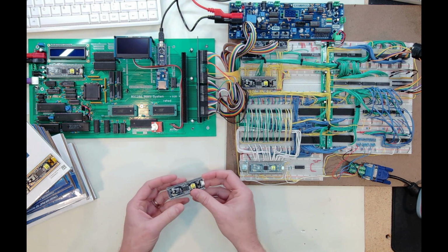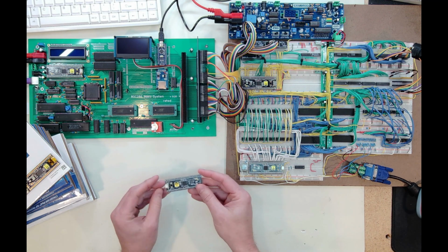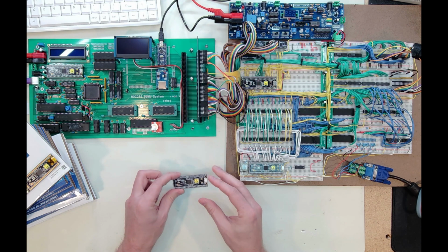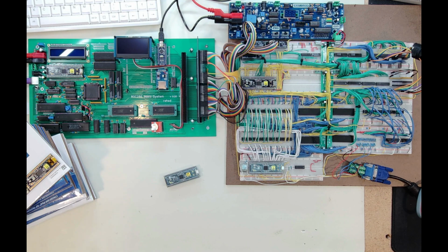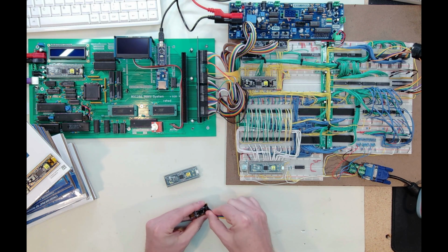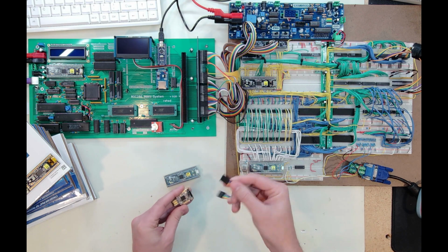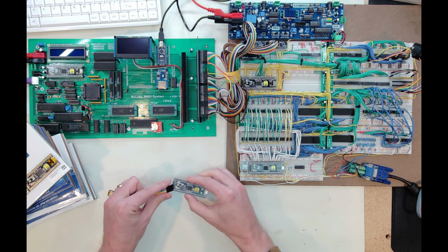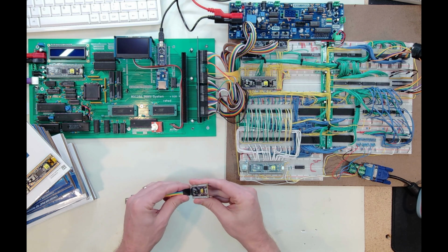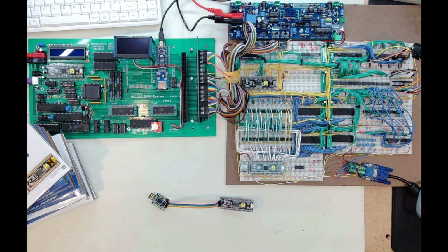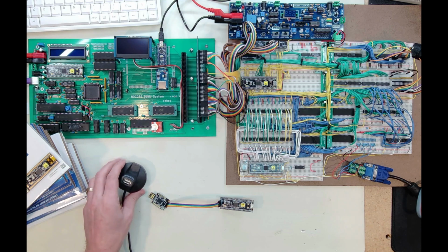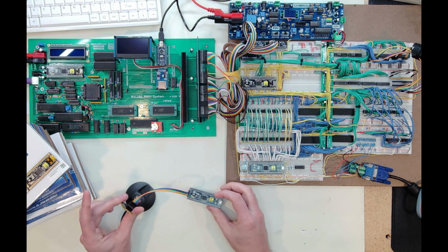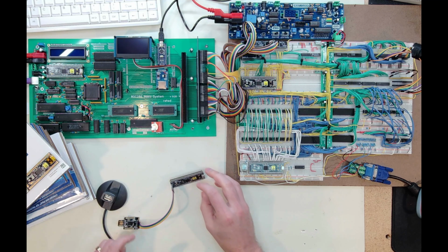So this one, I've done that soldering. I've got all my pin headers put in. I've got this up here so that I can do the programming. And then here's the programmer part of it. So just a little header, I grab my wires like so, and I can go ahead and connect that up, something like this. And then I need a connection to my PC for USB, and so here's my USB connection, and I can simply plug that in, and now I'll be able to program this PSoC.